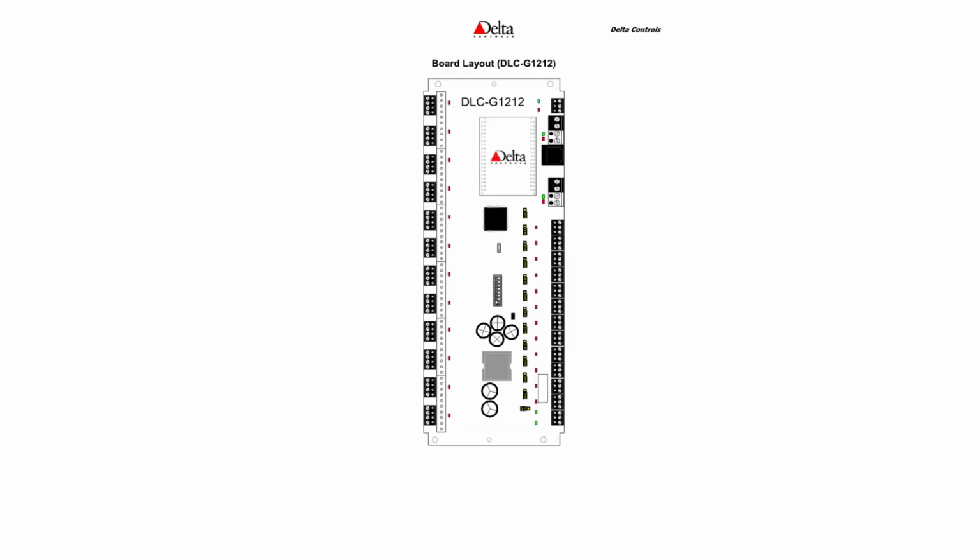Okay. Low voltage lighting controller, which is controlled sometimes by a standalone system with a time clock on it, or in our case in this UKB building, our lighting control is controlled by the EST Delta system controls. So on the lighting controller, you have a whole bunch of circuit boards. One circuit board, this black strip here, is where you connect the relay to, from the previous single line, on the low voltage side. So this is strictly low voltage side. You connect the relay to here in order to energize low voltage, which will connect up the high voltage on the contact for the light itself.